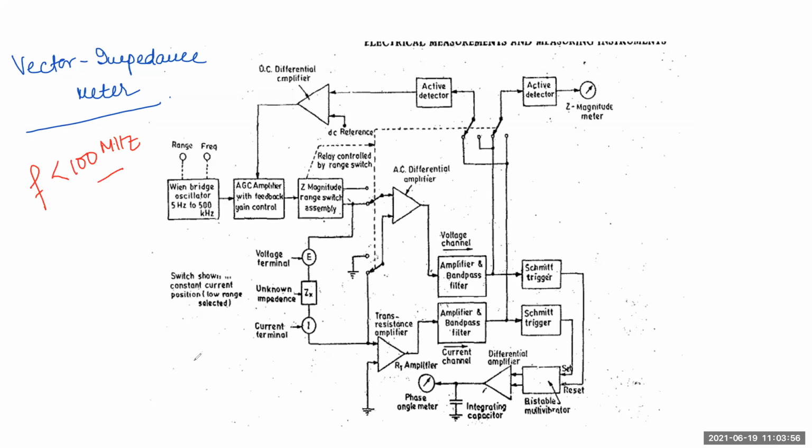Now, the phase difference between the voltage waveform and current waveform, we have to check whether your component is inductive or capacitive. From that, you can easily determine the phase angle. Now, CRO is connected to this portion because we can determine the phase angle by using a CRO.